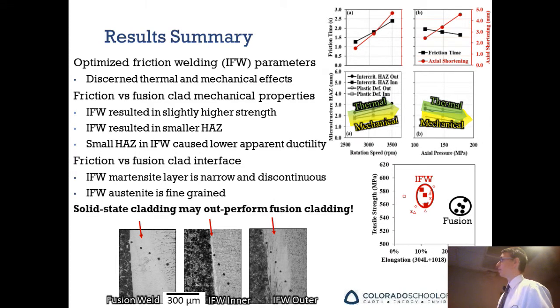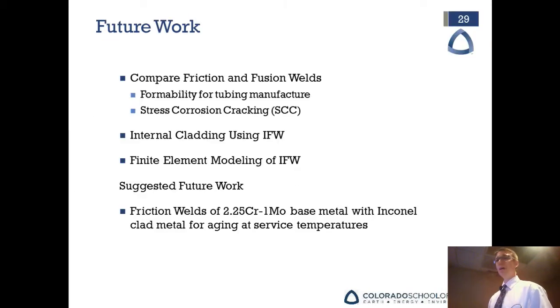So the big takeaway is that solid state cladding may outperform fusion cladding if we can figure out good application processes, a good way to apply that mechanical deformation at the same time as we do the heating. So it's possible there's a good application space for solid state welding and cladding.